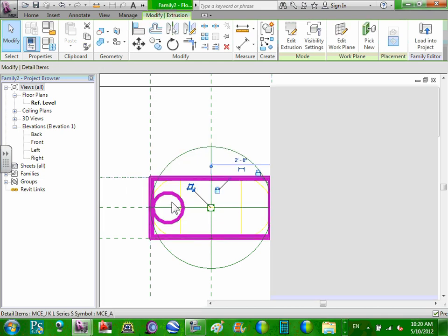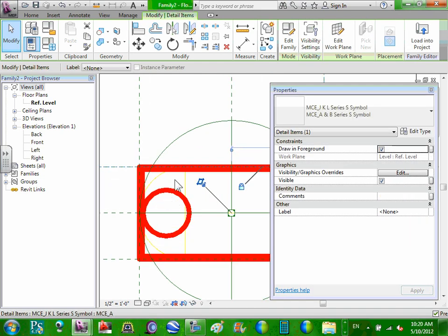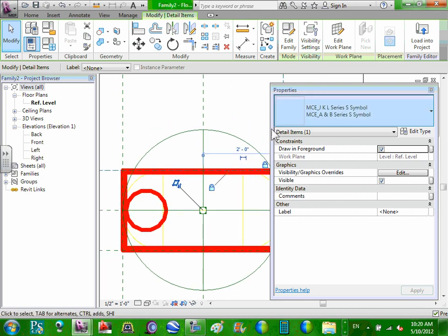Say, if I had those parabolic lenses or whatever, and there's 24 little spaces in this fixture, maybe I only want that to show up in a very fine view. So I take that extrusion, select it, and say you only show up in a fine view. In a regular coarse view, if you just throw it up in 3D, I don't need that. I just need the actual rectangle box.